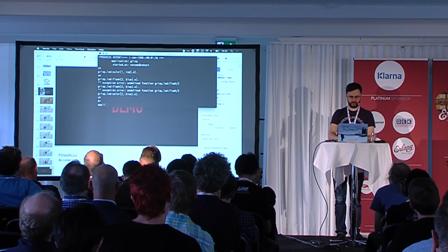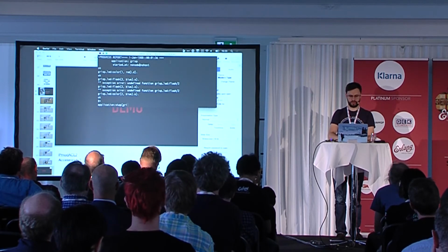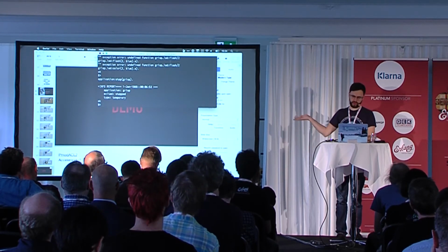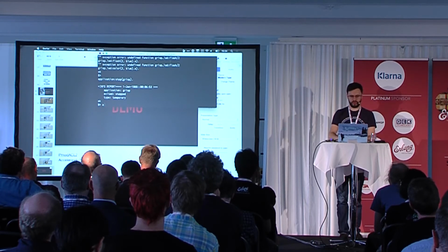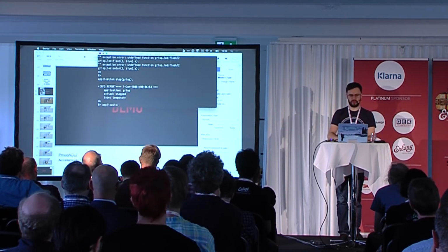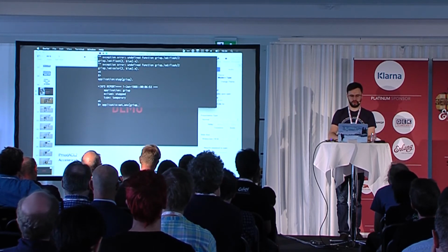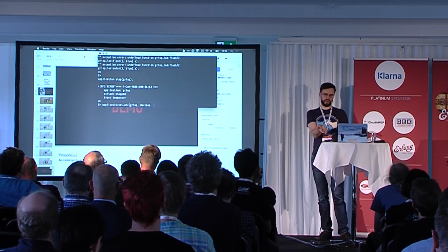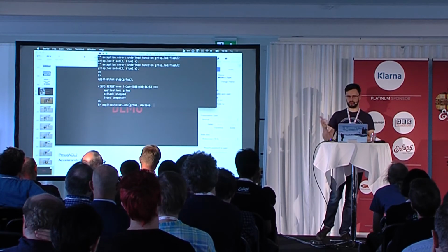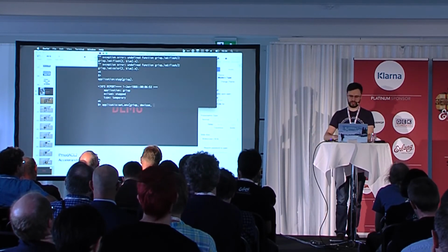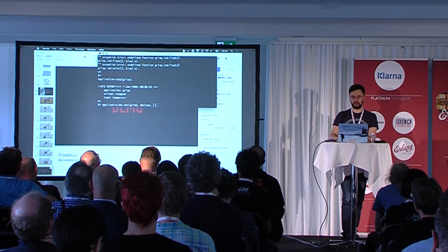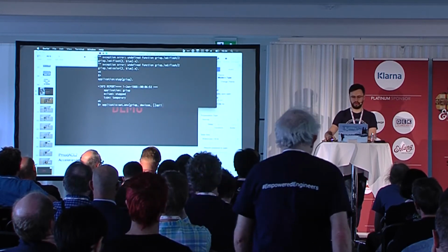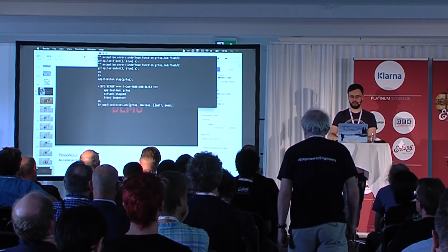So I'm going to stop this one. Now the runtime is stopped, basically. The hardware doesn't really care, but the runtime shut down everything. And I'm going to tell the GRiSP application that we have some devices connected. The way this works is that you could either configure it in your sysconfig or dynamically like this, or maybe we add some API for plugging and unplugging devices later. But this is equivalent. So we say that on the SPI port 1, which is this one, the extended one, we now have something connected. And this is a PMOD ACL2.